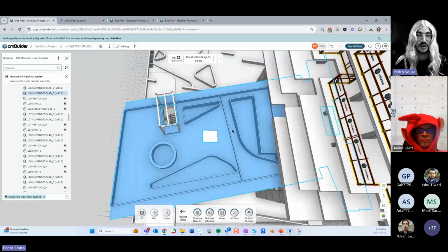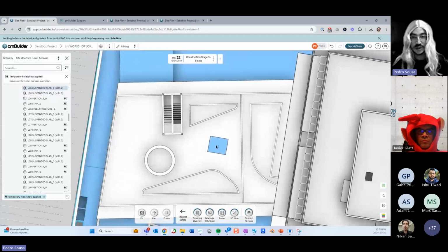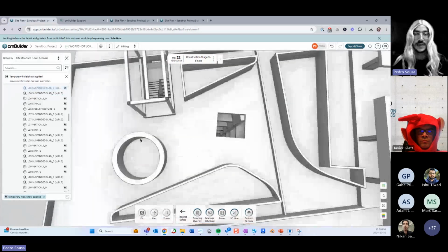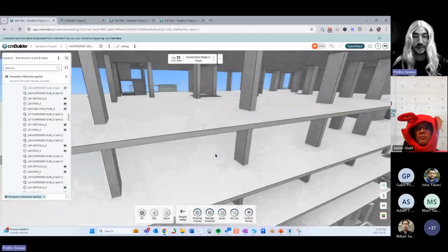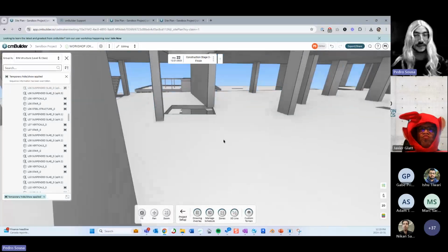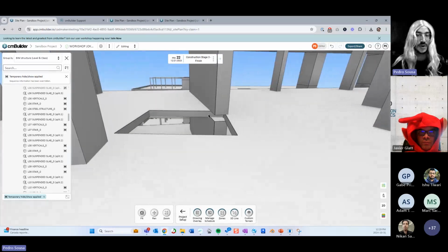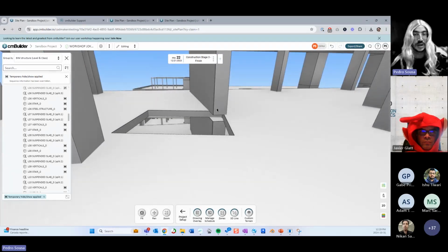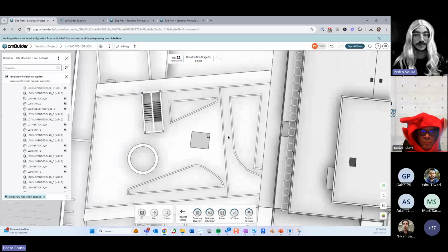So every time you're creating your sequencing for these amenity levels, you can just keep these parts out, and then in the end, you bring them back again to show that you were actually filling them back in. It's a great tool because you can check things like how the placement of the crane in your construction analysis will impact the design, right? It's a great way for you to visualize these elements in context.